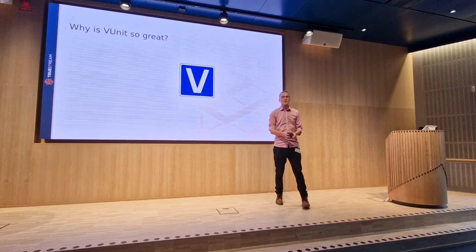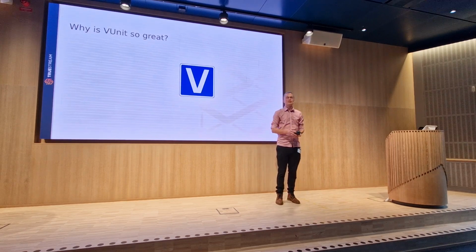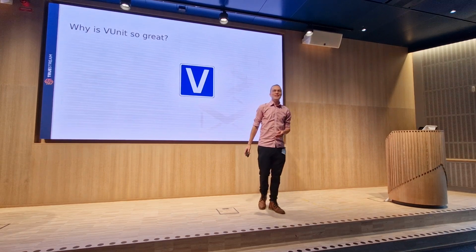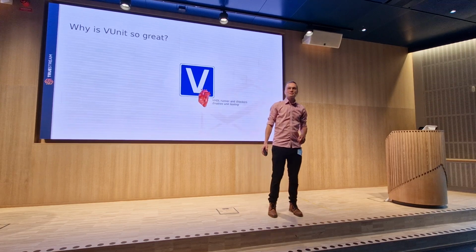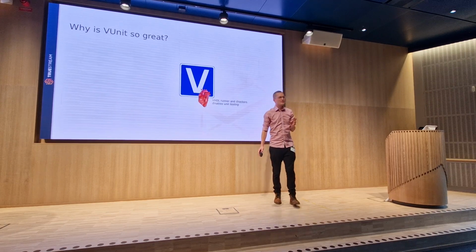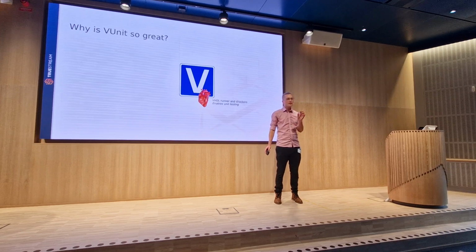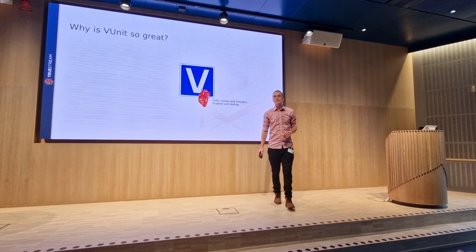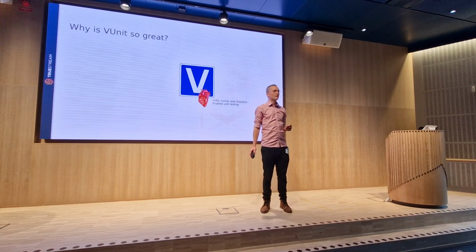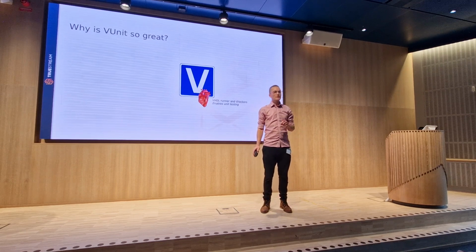So why is VUnit so great? I'm not biased at all. Let's go through the anatomy quickly. At the heart, we have the very basic stuff that lets you make a test as simple as possible in the VHDL domain. We have the VHDL runner and we have the checker functions Sebastian mentioned earlier.